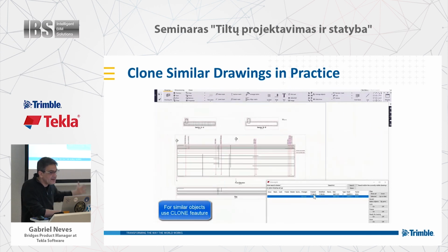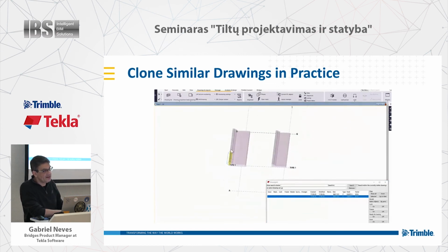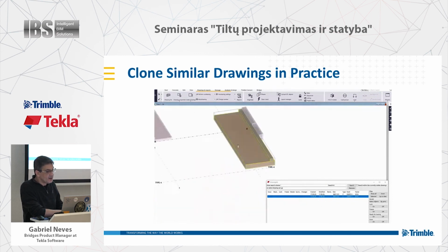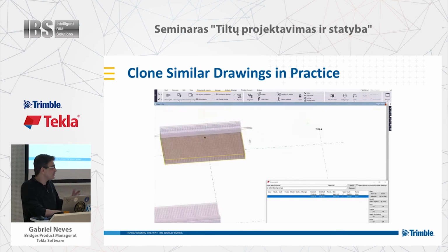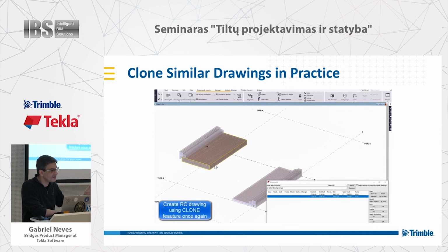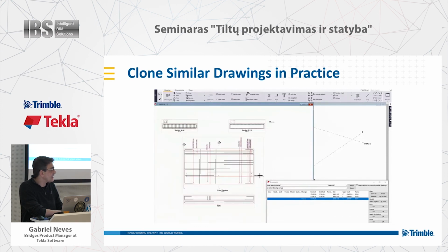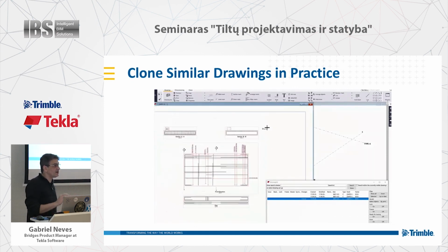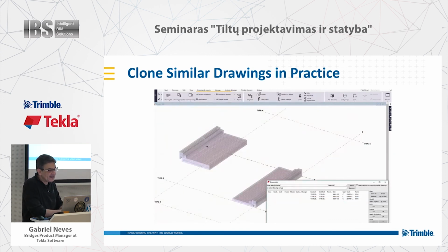This is the biggest advantage we have in Tekla when we are talking about being efficient and comparing with the market. Because we can invest some time to do the first abutment, the second abutment is fast. We spend some time to do the first pier, the second pier is a couple of minutes. The same way as you see here. So I deleted some objects there, created an even smaller one, and I cloned again. Then I go there and tweak and make sure. Don't always trust 100% in the software, and that's it. So it's a very fast video.